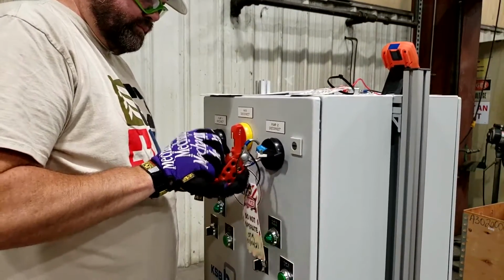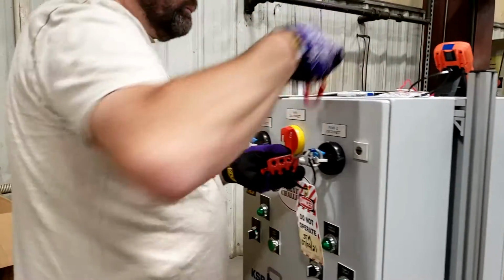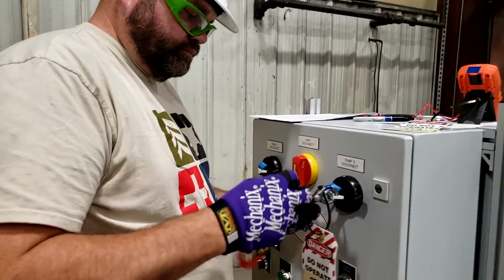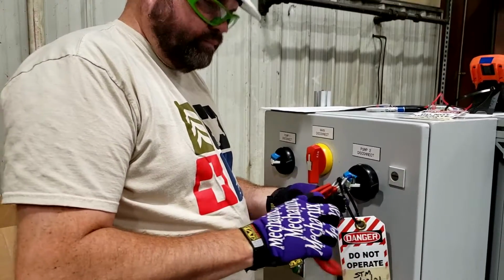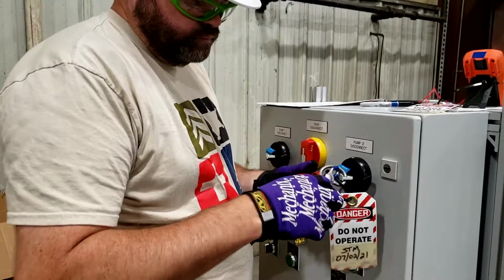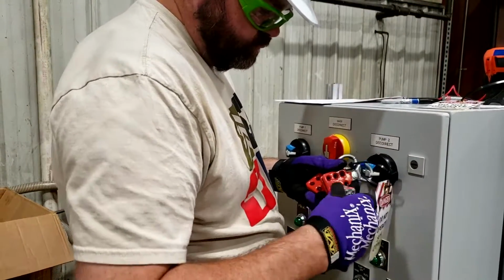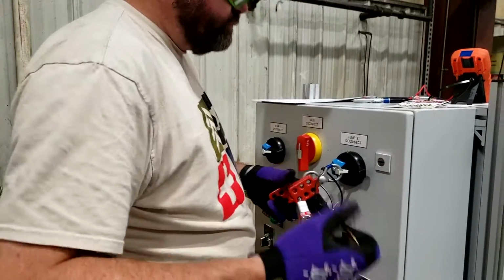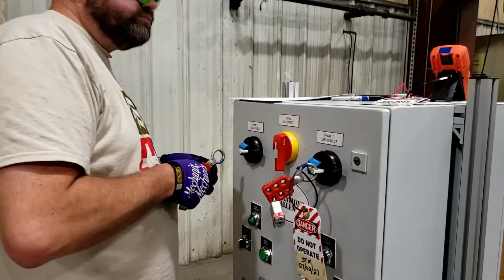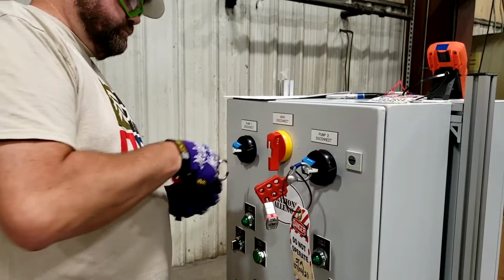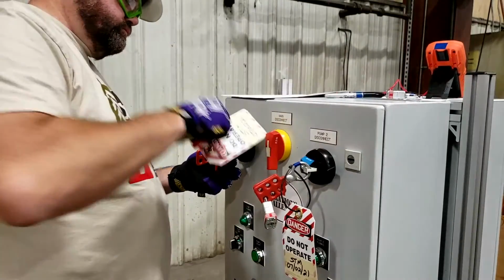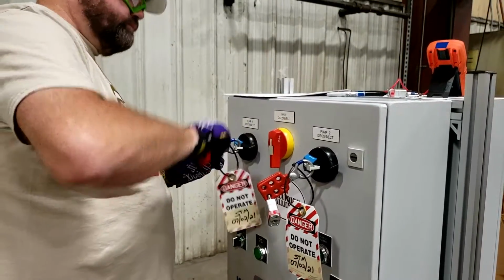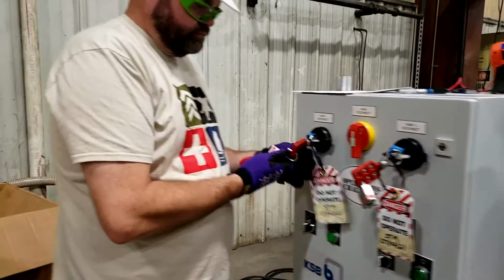There will be a zip tie on the lockout tagout tag. You must use the zip tie loop to hang from the gang hasp, not the eyelet on the tag. The zip tie shall be looped through the tag eyelet prior to the event starting. After the supervisor's lock has been installed, all remaining team members can lock out as necessary.